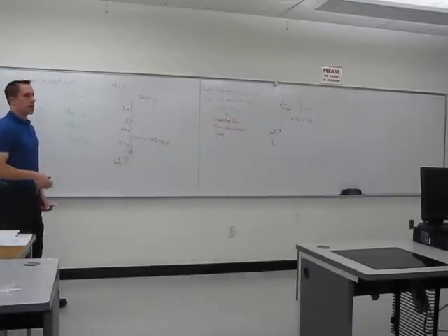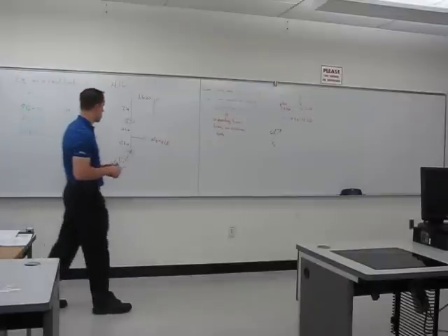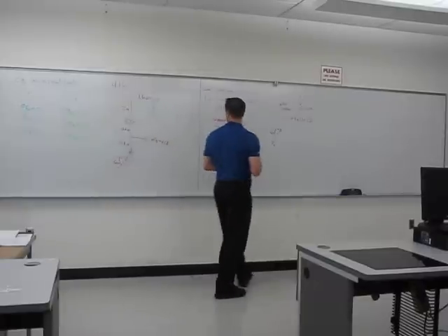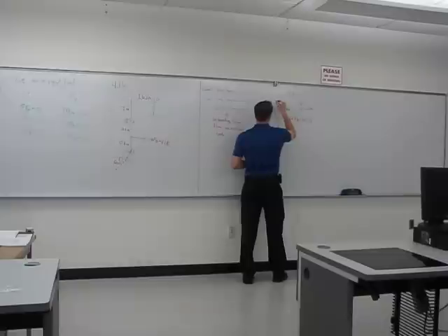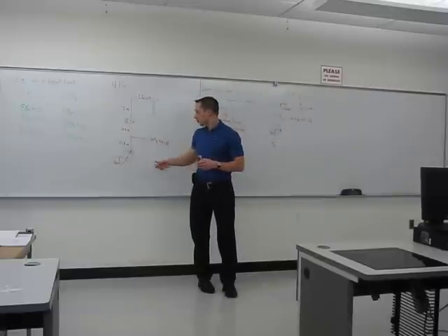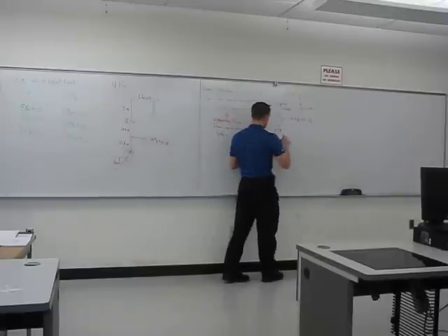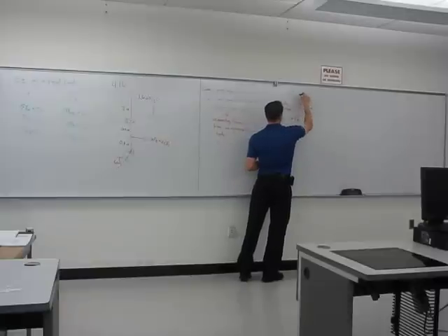So a free body diagram is just a simplified sketch of the rigid body with all of the forces. If you want to put the dimensions on there as well, you can. So you have like 1.6 inches up here, 2 inches, 0.8 inches, and 0.8 inches. That might be helpful as well. If you want to put the point names, you can even put those, point A, B, C, and D.